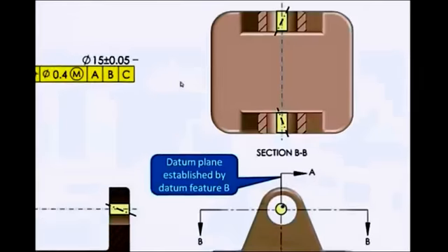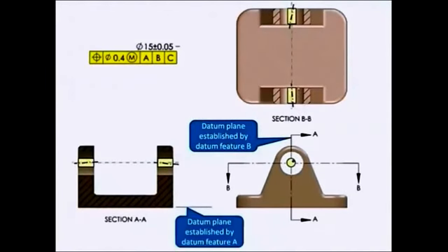In the first tip, we started with a position tolerance on these two holes that are shown coaxial on the drawing. But if we looked at what could actually happen to each one of these holes with this position tolerance of 0.4, we saw that the axes of the holes individually can tip around quite a bit. So they didn't stay in line by more than 0.4.